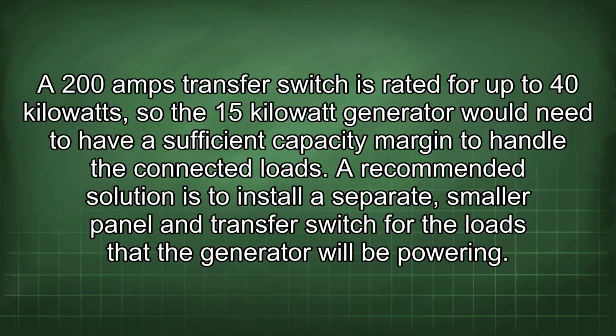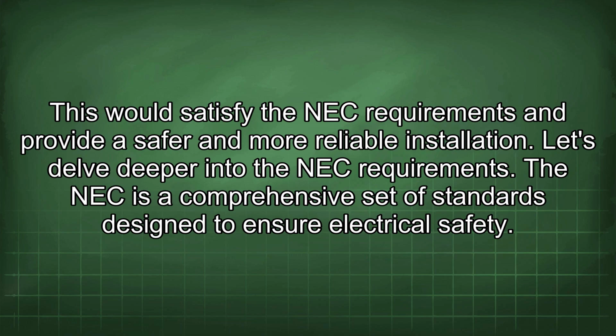A recommended solution is to install a separate, smaller panel and transfer switch for the loads that the generator will be powering. This would satisfy the NEC requirements and provide a safer and more reliable installation.